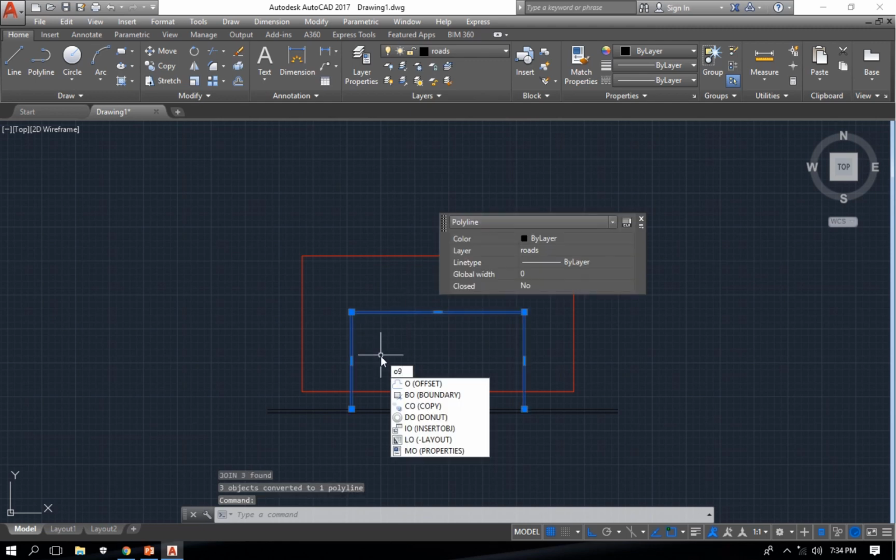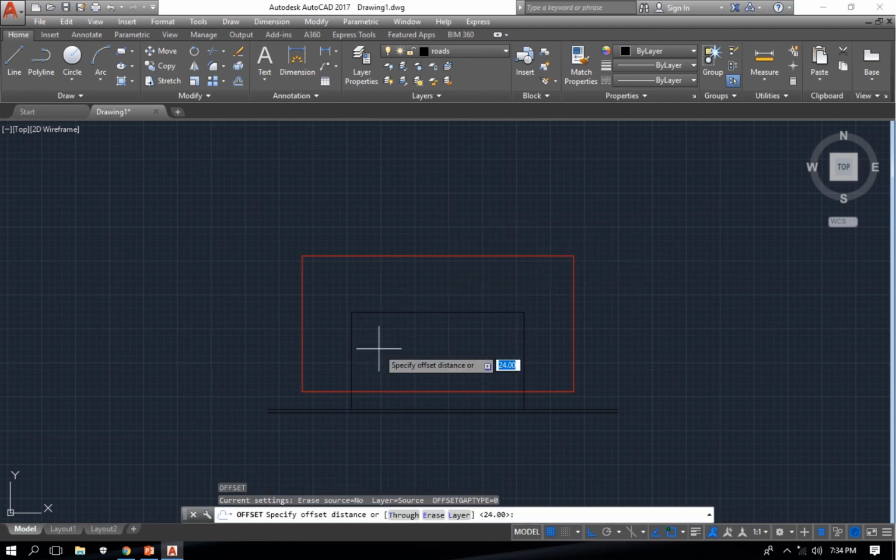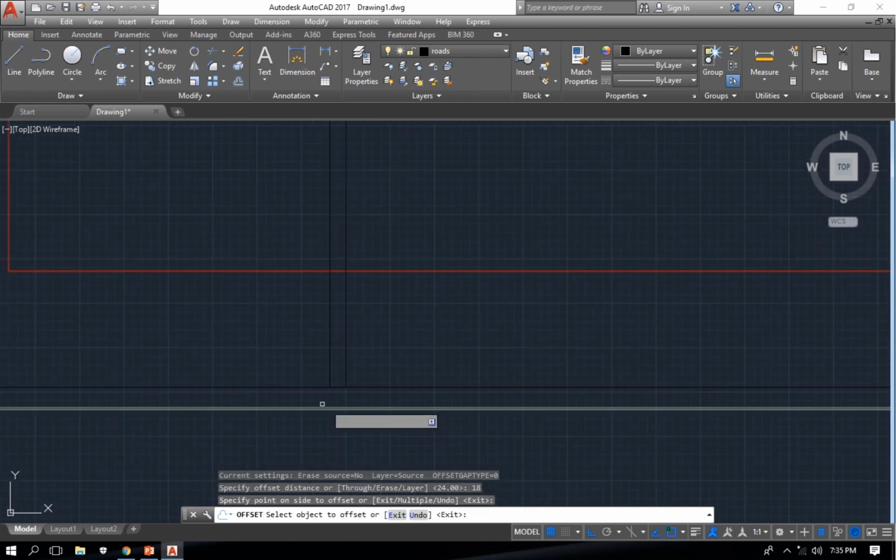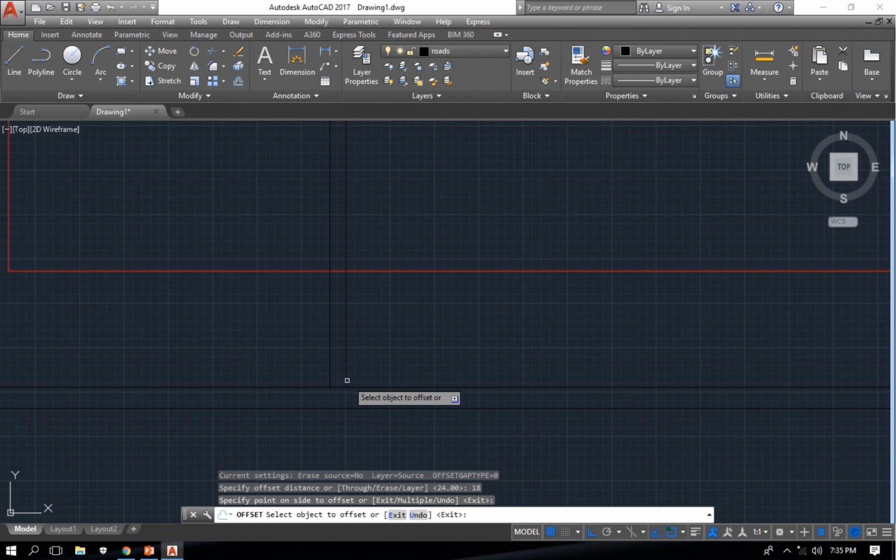Then offset to, let's make it 18, because usually the roads that link to each other are not the same thing. There's something called hierarchy of roads. So maybe in our next videos we'll be explaining in detail the hierarchy of roads and the rest of it. So moving on, 18 meters in width for this road. This is a different one. Notice it's slightly wider.